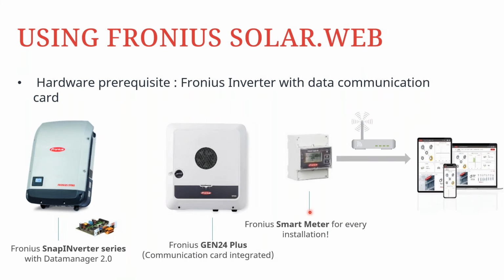Let's have a brief look at this SolarWeb remote update. Please ensure that whatever device you're using has a communication module in it. Without a communication module, of course, there's no way that the inverter can communicate. For the Snap inverters, ensure that you have a data manager in it if it's a single inverter. For multiple inverters, ensure that the master has the data manager. If you have multiple data managers, ensure that you have just one data manager that is turned in the on